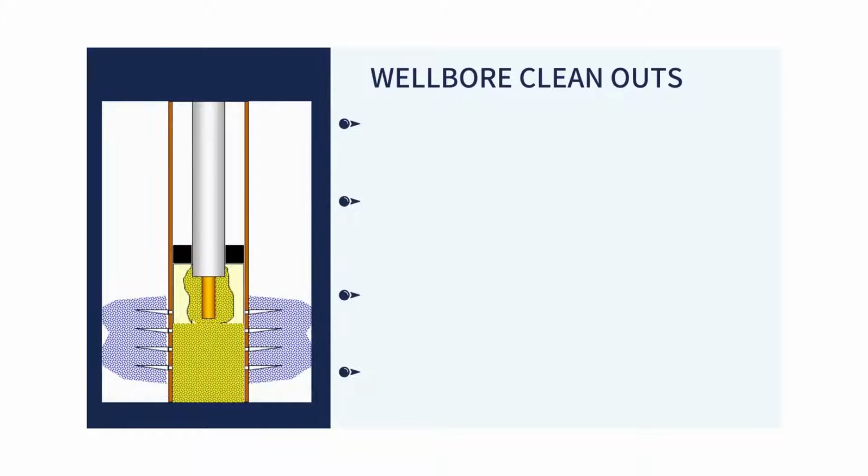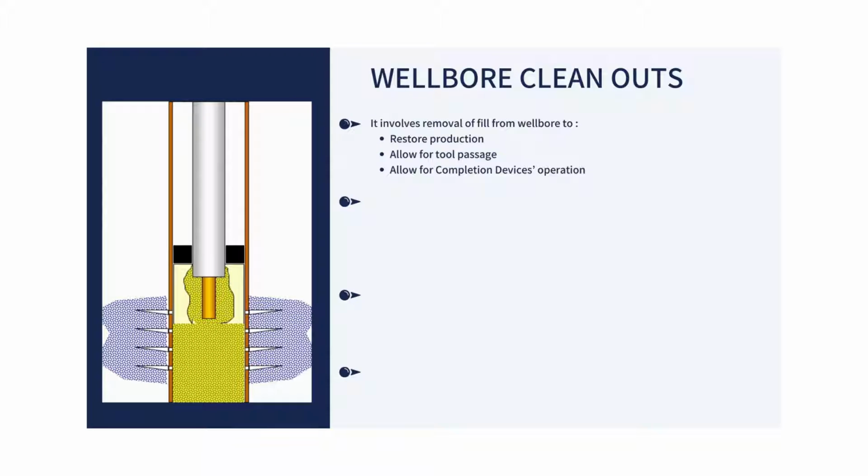Moving to wellbore cleanouts. It involves removal of fill from the wellbore to restore production, allow for tool passage, and allow for completion devices operation. The system is sensitive to fluid viscosity, fluid velocity, wellbore deviation, and bottom hole pressure.